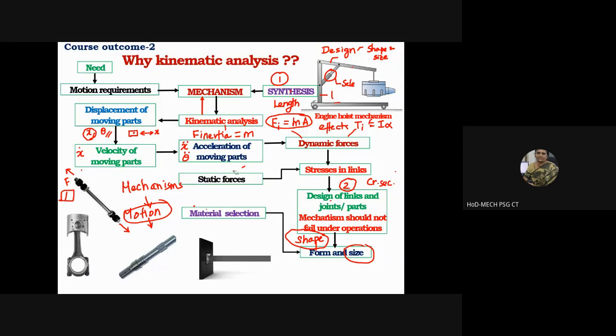Apart from including the static forces, let me explain with this example. When I say static forces, what is the major force that comes on this? It is the weight of the engine. So this weight of the engine will cause this to experience some force. There will be a force acting here also. There will be a force, bending moment, and torsion moment also probably acting on this link. So all of these will be subjected to forces.